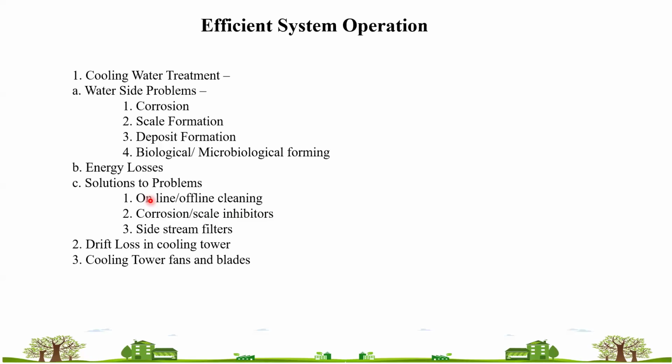There will be building load also, and there will be human load also. Latent load is adding, so your PCs would be on, your laptops would be on. There will be motive load, human load would be there. So both loads cannot be catered by a system. So building has to be pre-cooled.